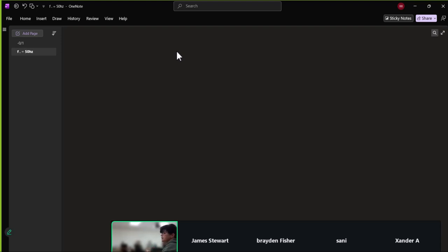So if our impedance is R plus jX, the more this jX part is, the less your real power is going to be and the more your reactive power is going to be. So you want this part to be zero.